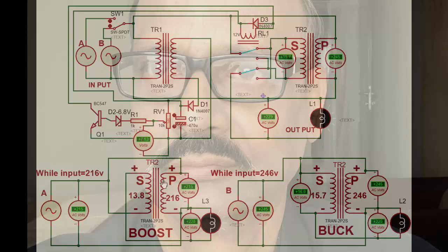And this plus minus, as I told you, is nothing. There is nothing like plus or minus in AC. It is just a polarity to be understood. It is the instantaneous value. That means in the positive half cycle, this becomes positive and this is negative, and in the next half cycle, this becomes positive and this becomes negative. This is for better understanding, but actually it is the polarity which is considered in engineering terms, or what we discussed as in phase and out of phase. This is an in phase situation where the voltage is boosted. This is an out of phase situation where the voltage is subtracted.